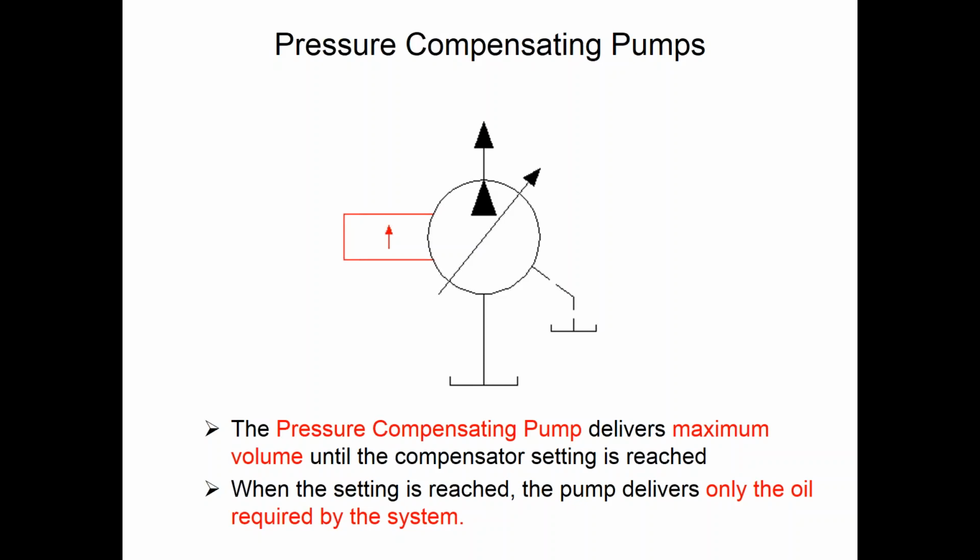Right? This pump is the culprit right here that keeps people from understanding the difference between pressure and flow, or more to the point, thinking that the pump pumps pressure. And quite obviously, if there's a knob on the pump, and if you turn the knob, the pressure changes in the system, then apparently that pump is pumping the pressure, and you're determining how much pressure it pumps. Well, no, that's not what you're doing. What you're doing when you adjust a pressure compensating pump is you're adjusting the point at which the pump will stroke or de-stroke to increase or decrease the flow.